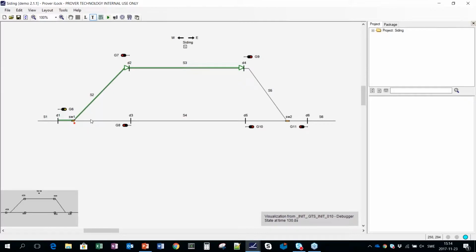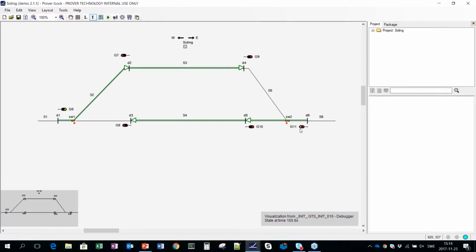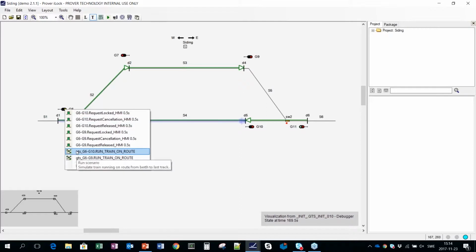This is an example of something that has been generically defined in the generic application. Whenever there is a route over a reverse switch, it will be signaled with a yellow aspect. If there is no switch or only straight switches, the aspect will be green. So for example, if I have a simultaneous entrance here, on this one, we can see that it is green in the main signal, saying you can proceed with an unrestricted speed, but then red because the next signal is at red.